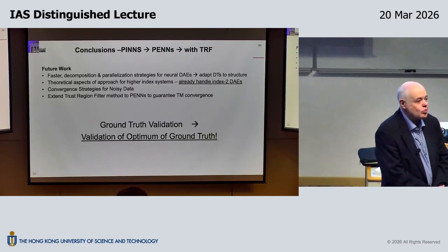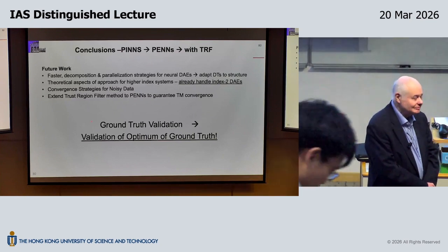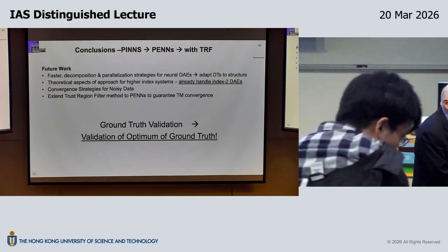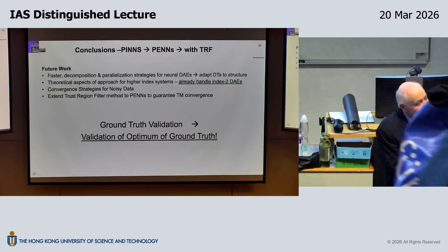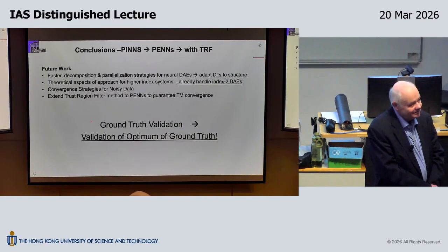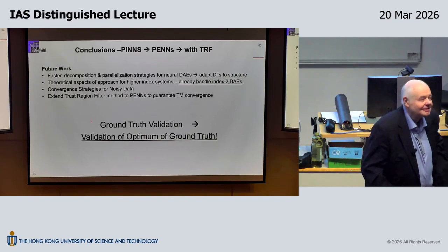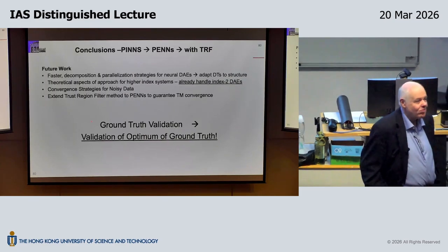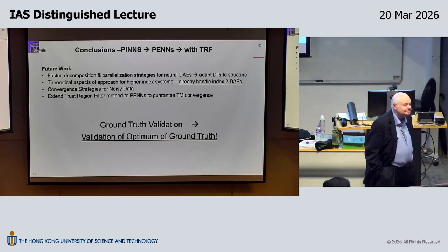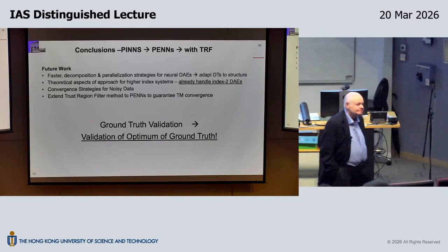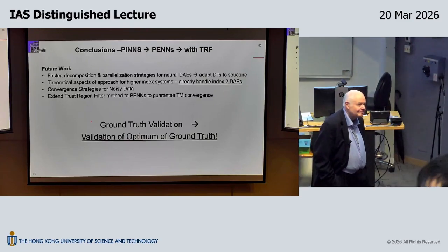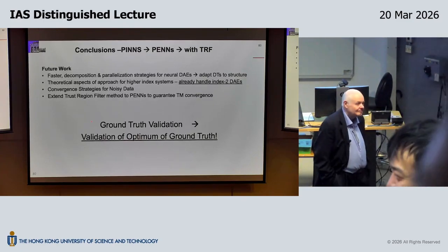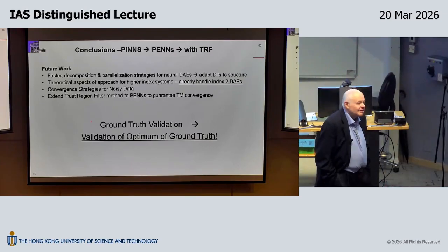About the surrogate model, what PSE people did, for example Marinati, I'm also doing that. For process optimization with a complex reactor module, we tend to train a Gaussian offline with 30 data points, and then pass that Gaussian to IPOPT to solve the problem. When IPOPT gives us a solution, we check if the solution is feasible. If it's not feasible, we add that data point to the Gaussian, retrain the Gaussian, then pass it to the model again. So how does this trust region filter method compare to this traditional methodology?